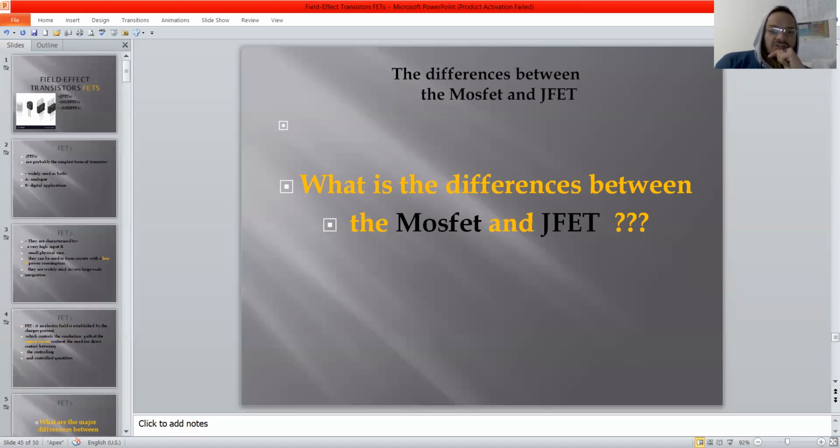A positive voltage at the drain source voltage is applied across the channel. Let's take 2 volts and more: start from 2 volts, and after that increase. The gate is connected directly to the source to establish the condition that the gate source voltage equals 0.